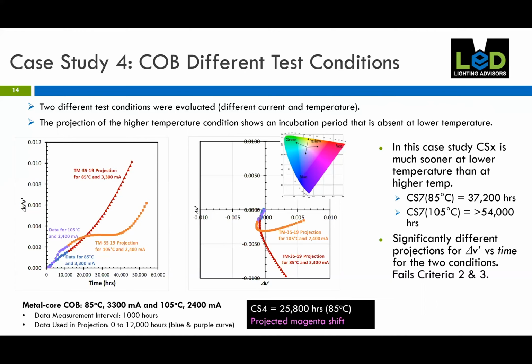It would require a very challenging set of circumstances coming together simultaneously to result in the shift, which was never observed. For example, if the relative red emissions increase while the blue emissions are also decreasing simultaneously, then you could get a shift in the magenta direction from the data, but these 2 trends are mutually exclusive and unlikely to happen simultaneously in the white phosphor converted LED, because an increase in blue emission means that more photons are bypassing the phosphor layer and not being converted to increase the red emissions.